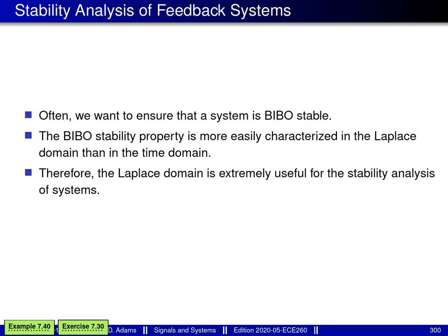In order for a system to be of practical use, whether it be a control system or some other type of system, the system typically must be designed to satisfy a number of performance and safety criteria. For obvious reasons, safety criteria are extremely important. In many applications, a critical criterion for safety is BIBO stability. If a system is not BIBO stable, this means that a finite input to the system can result in an unbounded, in other words infinite, output.